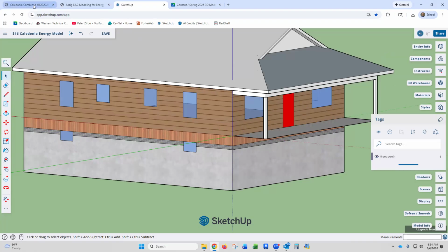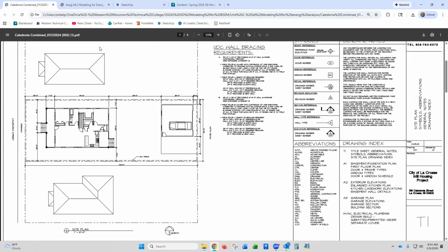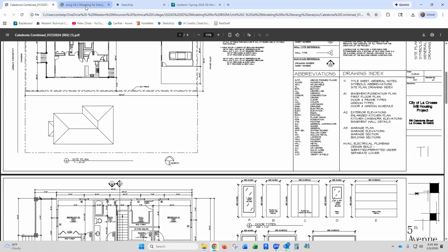Now, the other thing that's important is this one's nice and straightforward because north is up. In order to have the solar axis right, we need to have it oriented right. When you draw it in plan for the first time, north is up typically, like a graphic standard, and that's how this is drawn. So you can draw this in SketchUp in plan view exactly the way it's shown here. If you don't draw it with north up, when you start turning the shadows on, you'll notice that north's not up. It's very easy to draw a box around everything and rotate it however many degrees you need to get north to be up. So the assignment here